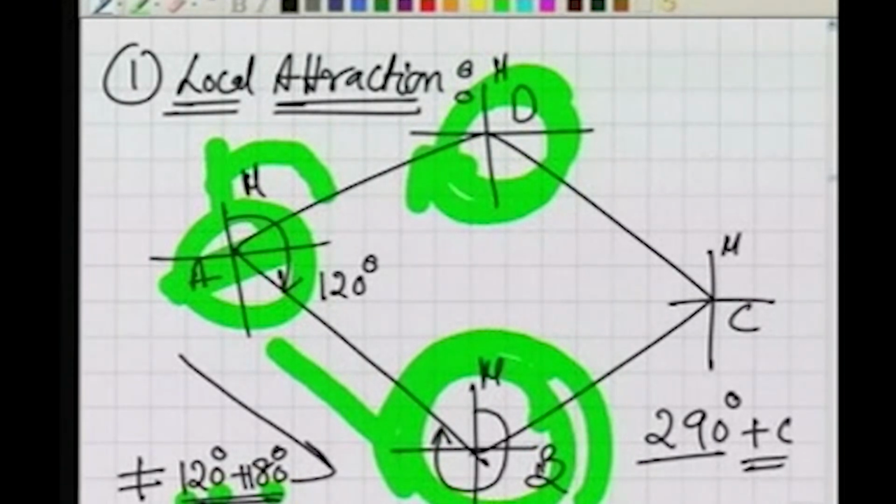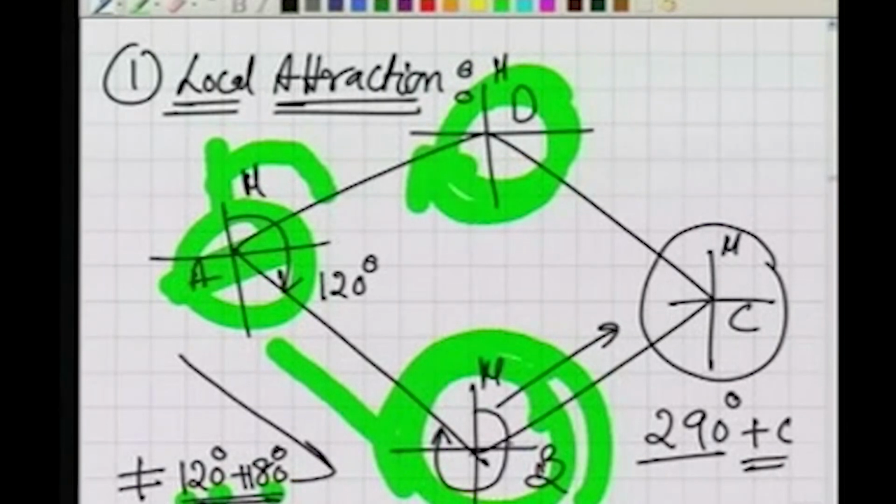So that amount of correction will be applied here. If we apply this particular correction here, the same correction should also be applicable in this direction. So this should make the difference of back bearing and fore bearing of line BC again equal to 180. So this is how we are applying the corrections.